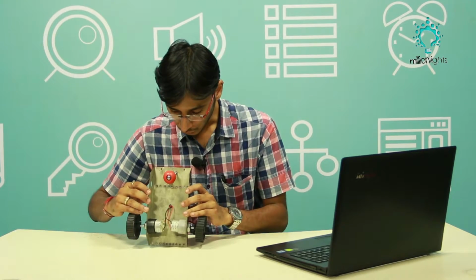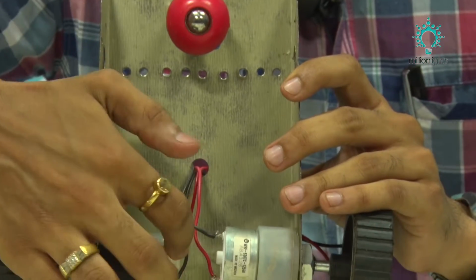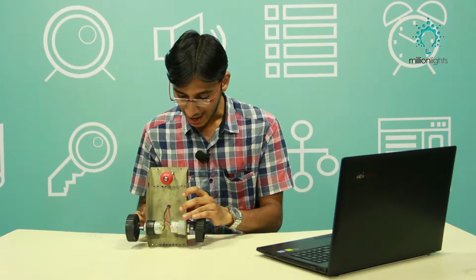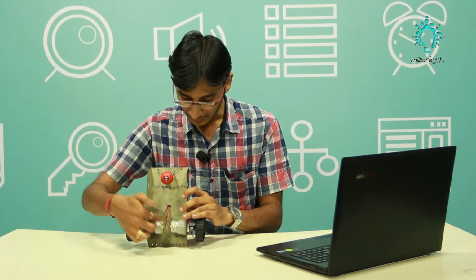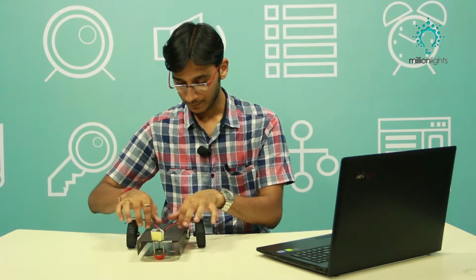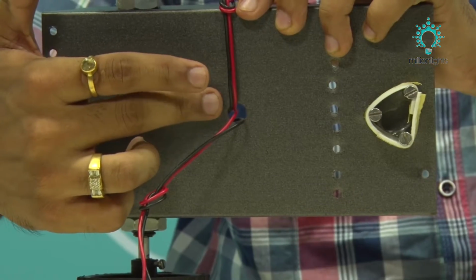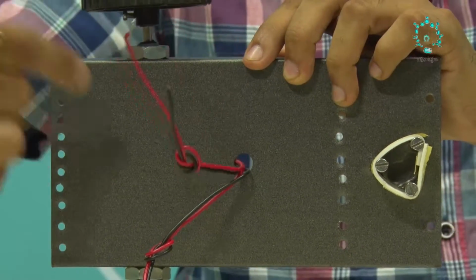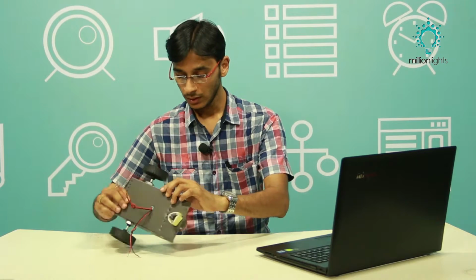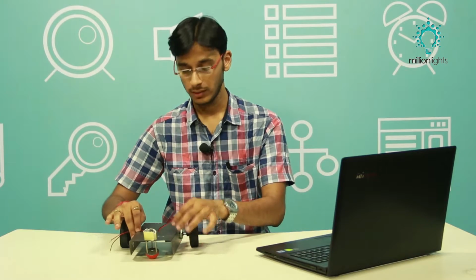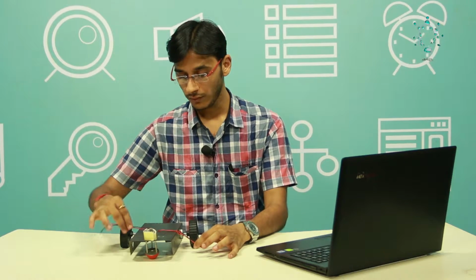Now one more thing I would like to show is that the two terminals of your motor are connected, and I have connected them according to the colors and taken them up. So in a lot of chassis you have a central section which has this hollow, or if it is not there you can drill it, or you can make a hole and take these things out. So I have taken these out. What it does is it allows me to control the motors. So this is the left motor, this is the right motor. Now with the help of Arduino or L293D I can control the direction.